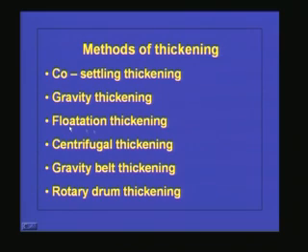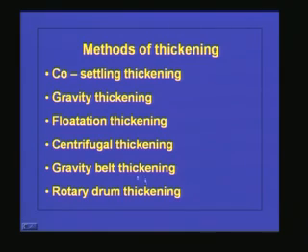Flotation unit, we all know, if the solids density is less, then instead of going for gravity settling, we can concentrate it by flotation. So flotation also we have discussed in detail when we were discussing the solid removal. And centrifugal thickening, here we use the centrifugal force for the thickening.